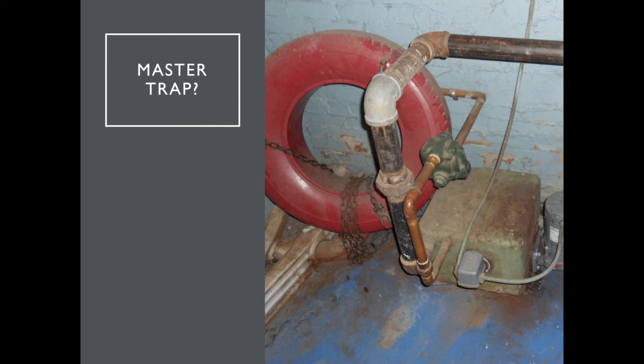Thank you, Ray. And Hubert asks, I work at a commercial property in New York City. Should my boiler supply fan be interlocked with the low pressure boiler? Yes. It's part of the code. You want to be able to make sure that the combustion air is working before the boiler comes on.